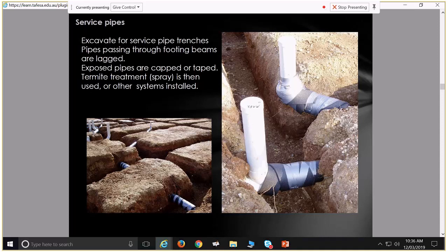Once you get cracked pipes underneath the slab, you get moisture, you get more swelling, you get exacerbation of that issue, and then your pipe gets cracked worse, and it's very difficult to repair a pipe underneath the slab. You can sleeve them and things like that, but it's not much fun. Sometimes you've just got to cut through the slab and jackhammer away that concrete, repair that pipe, and then you've got a compromised slab. The way you deal with that is you drill into the sides of your slab, reinstate steel mesh, chem set that mesh into the rest of the slab, and then pour back over again, so your steelwork is locked back into that slab. It's really quite a process. It's much better if you get this right to begin with. It costs hardly anything.